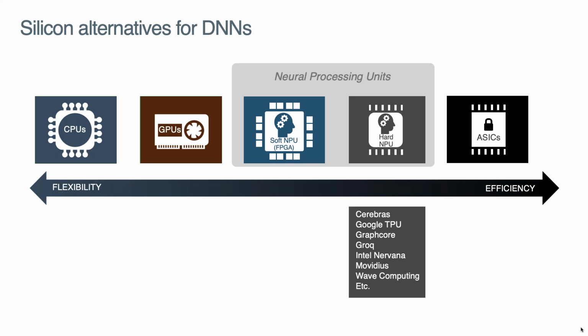The benefit of it, again, is that they do exactly what you want to do. The thing to consider about that is the time that it takes to be able to design a chip and test it and to tape it out, fab it, manufacture, et cetera, and get it into your data center could be about 2 years. Meaning that if we were to start today and create our own custom AI chip, we would not see it for about 2 years. And that's just the thing to consider when you're thinking about ASICs. So that's why, to keep up with the fast changing AI landscape, we're focusing on FPGAs.